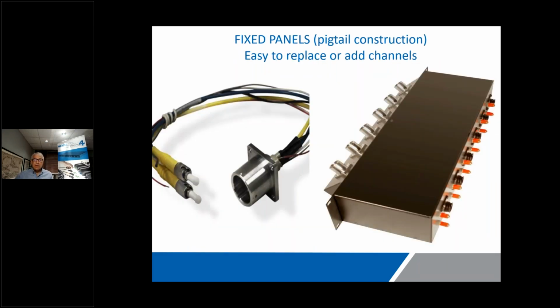I also like to emphasize in panels today, the pigtail design allows you to do modifications, additions, instant maintenance without ever having to terminate a SMPTE connector. Terminating a SMPTE connector is a very training intensive, time intensive, cost intensive procedure, and it's something that you probably don't want to do unless you're going to do a lot of them. So by having pigtails, you can buy replacements, you can keep spares, and you can immediately change them or add them as your needs dictate.